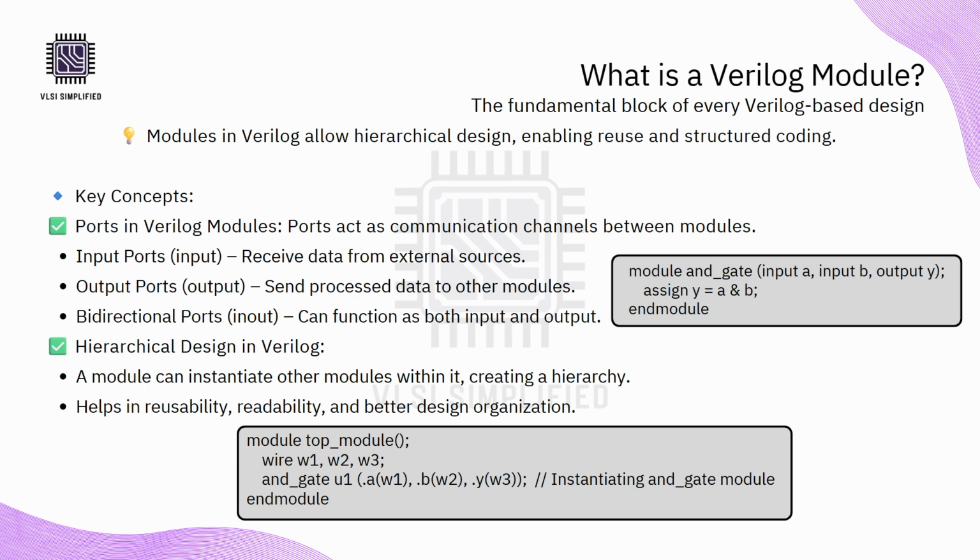You define a module once and you can instantiate it multiple times throughout your design, much like using the same chip in different places on a circuit board. Modules can also contain other modules, enabling hierarchical design, which is the key principle in complex hardware development.